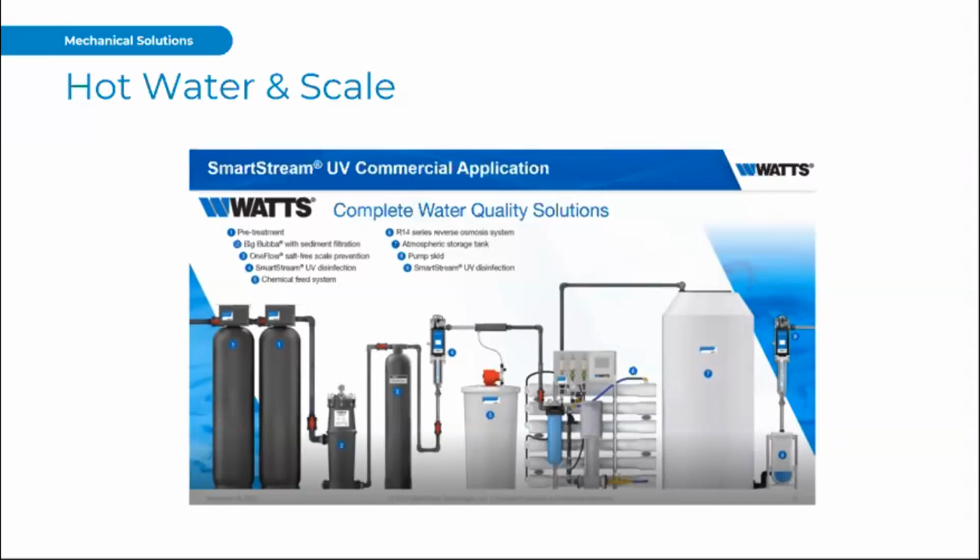And the most basic water quality need would be general softening. Of course, we have a variety of ways that we can help with your water softening. And if you provide us the water quality report, the Watts team will be able to take that in conjunction with your design parameters like your flow rate and your other requirements, and our team will assist with sizing and provide the full water softening solution and package.